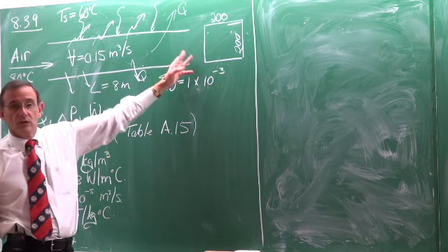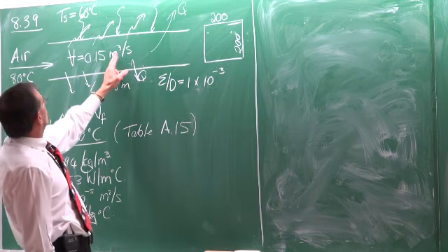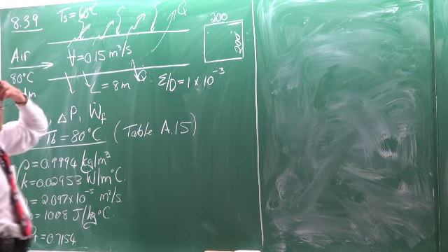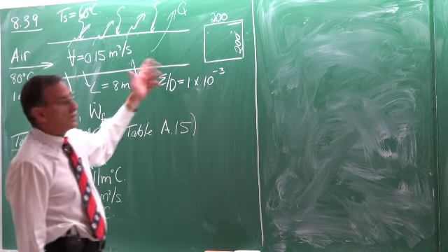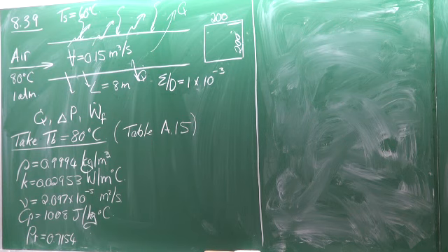We do not have the outlet temperature, so you can either guess maybe 70 degrees Celsius, or you can actually use 80 degrees Celsius, and then later on, when you have the outlet temperature, then you can get the bulk temperature and you can just do the problem again. So let's start in this case with the bulk temperature at 80 degrees Celsius.